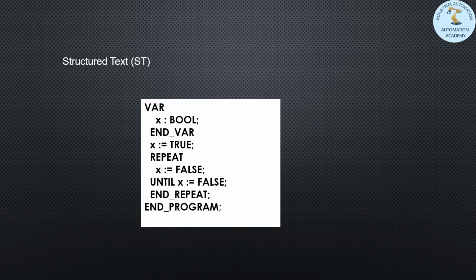Structured text looks very similar to BASIC or C programming. It is best used for control systems that require mathematics or complex tasks. Trigonometry, calculus, and data analysis can be implemented far easier in this language than in ladder diagrams. Because ST is not a graphical language, it runs faster and requires less memory. If you come from a traditional programming background, you can become proficient in ST faster than ladder logic or the other graphical PLC programming languages because the commands have a similar structure.